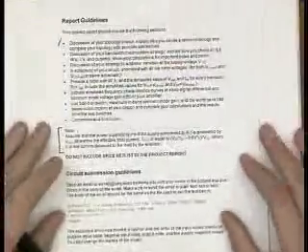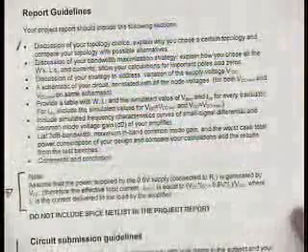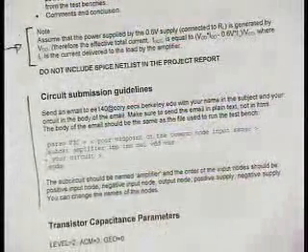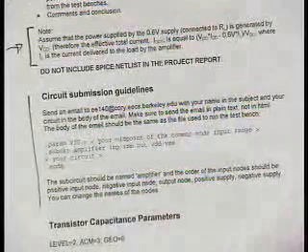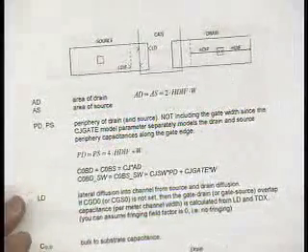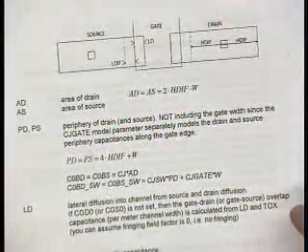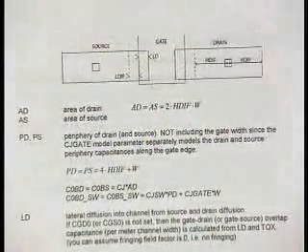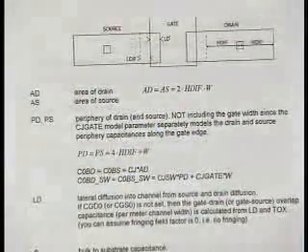What else do I want to talk about? Give me 1 second. All right, so going back to this handout, can we zoom in tight again? Thank you. So this note is what I just went through. Circuit submission guidelines are exactly the same. Now, people were asking, hey, there isn't a CGS or a CGD parameter in our device model. What gives? That's actually not true. There is, but it's just kind of implicit. So I wanted to go over really briefly how you calculate the area drain, area source, and the various device parasitics, okay, when it's not implicitly given.